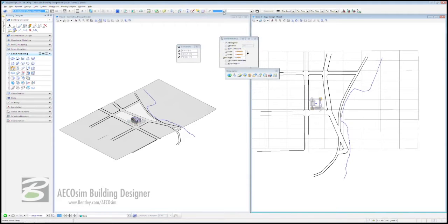Before we do that, we're going to select a part and family. We're going to select Site, and underneath that, we're going to select Earth. Now, the reason we do that is going to help us out in the long run, because it's imbuing our model with even more information. Now, our Solid by Extrusion dialog box is open. Make sure orthogonal is checked.